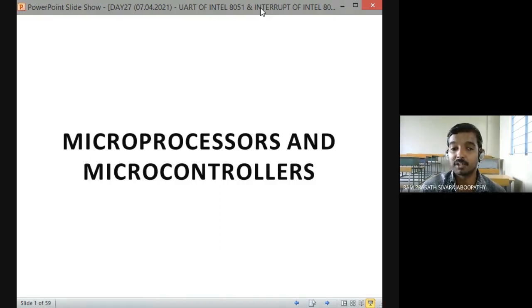After we have loaded the count value, what do we have to do? Once we have configured and loaded the count value, what do we have to do? Yes, we have to run the timer/counter. Very good. To run the timer/counter, which bit in TCON do we have to use? Type it in the chat. The TCON register is the timer control register. Yes, very good. TR1 and TR0: TR1 for timer/counter 1 and TR0 for timer/counter 0.